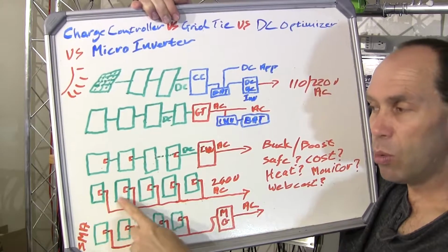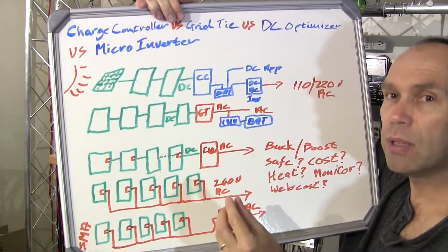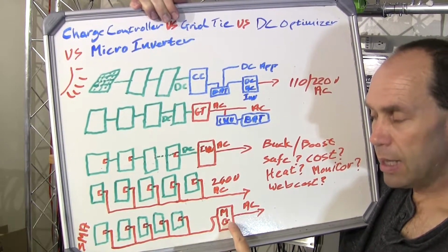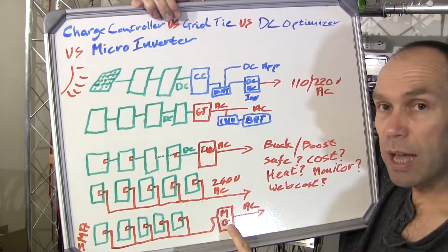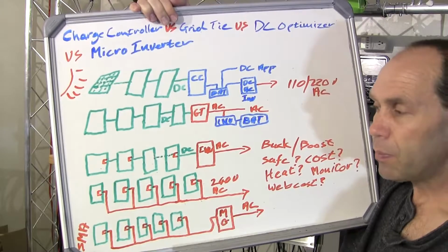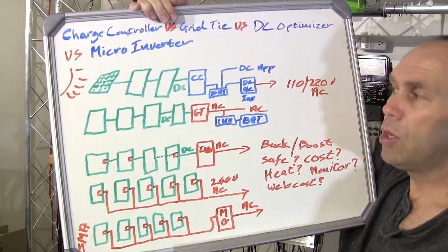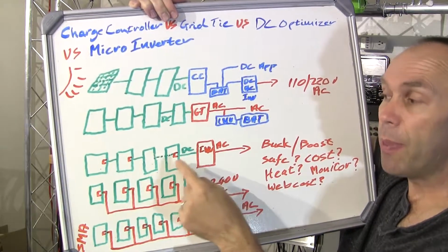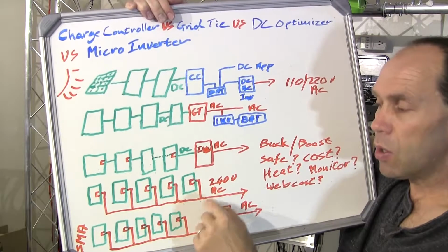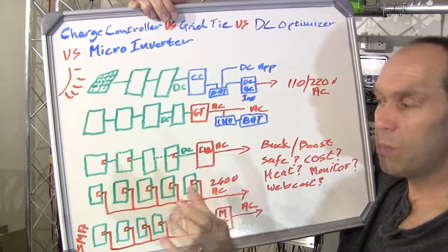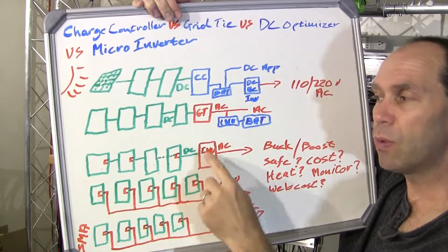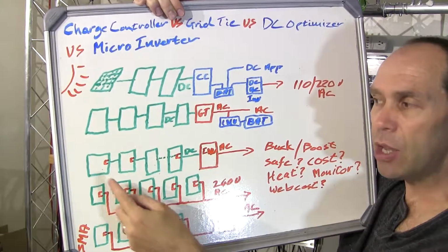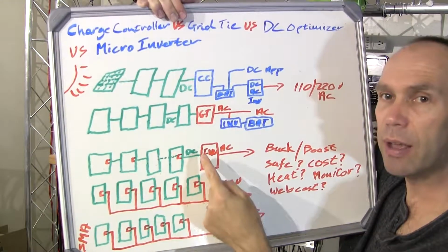One of the benefits with a normal microinverter system is that your single points of failure are potentially ruled out of the system. Whereas here on the SMA system, if your multi-gateway goes down, then your whole system goes down. So these are the things to be wary of. Now in terms of costs, obviously the DC optimizers per unit tend to be cheaper. They also tend to scale better as well. The costs on the microinverters are linear. You've got a fixed cost per microinverter, but apparently there are solutions for the DC optimizers that make it more economical once you start growing and scaling it. But again, you have to be aware that you've got these strings tied together and the limitations there.